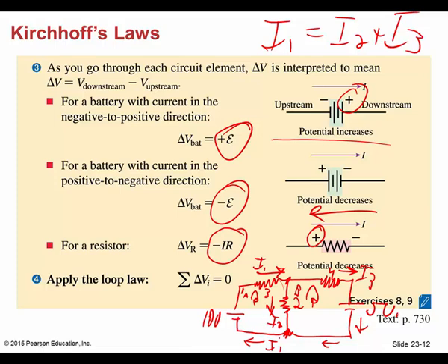We come all the way around this loop right here, and it would be minus 3 I1, and then I hit the I2 branch, going with current flow, and again that's arbitrary, minus 2 I2. Then we hit the junction and come back around. We hit the negative side and land on the positive, plus 10 volts, is equal to 0. Because remember, the sum of all the voltages is equal to 0. So that would be another equation.